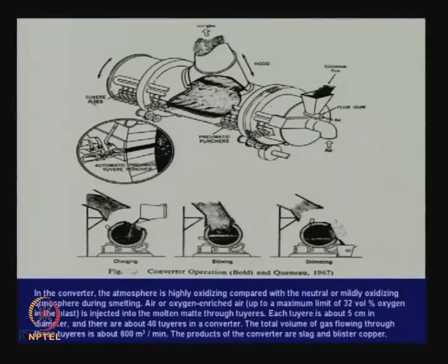There are 2 air pipes through which the oxygen will be blown in. There is intake of siliceous flux because you have to create a slag. There is a flux gun, through which the flux will be thrown into the converter, and so on. Gases will come out of here. All the details are there.